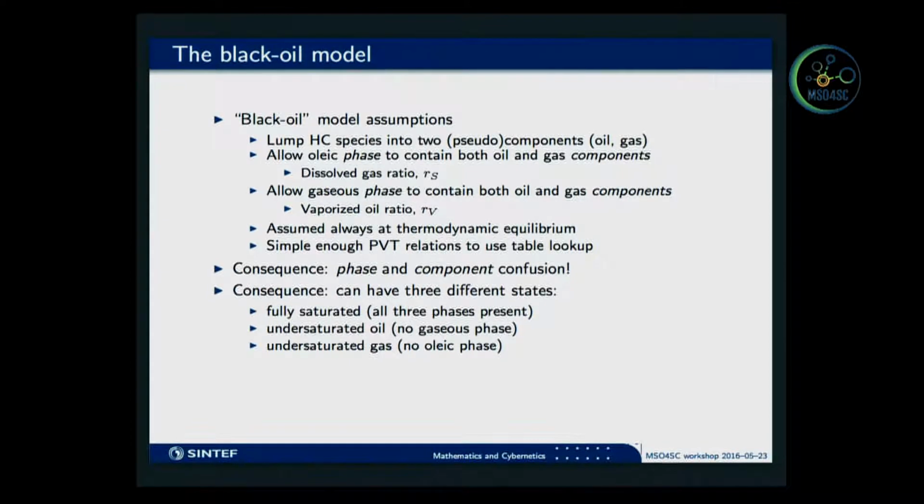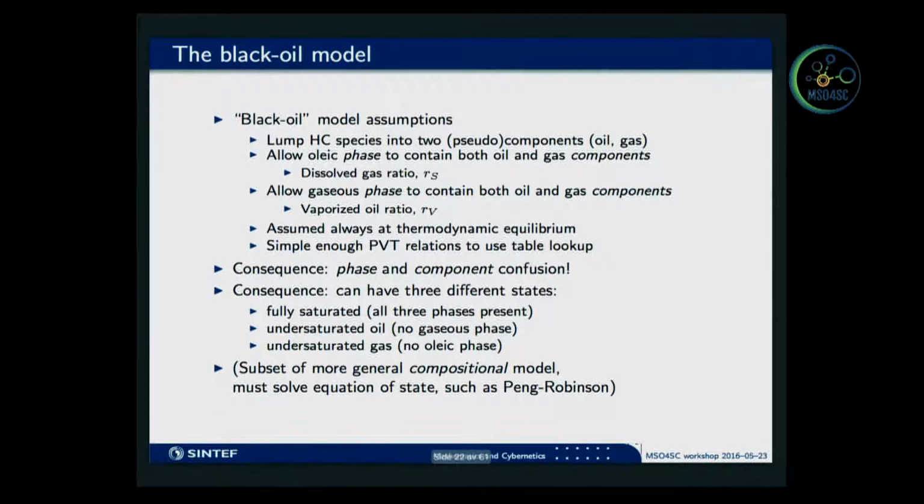Another consequence is that you have three different types of states at any point. You can have a fully saturated state when all three phases are present. You can have an undersaturated oil state when there's no gaseous phase. All the gas has dissolved into the oil phase and is still undersaturated, because when it gets saturated, then the excess gas has to go into its own phase. And there's an undersaturated gas possibility, which is just vice versa. All the oil has vaporized into the gas phase.